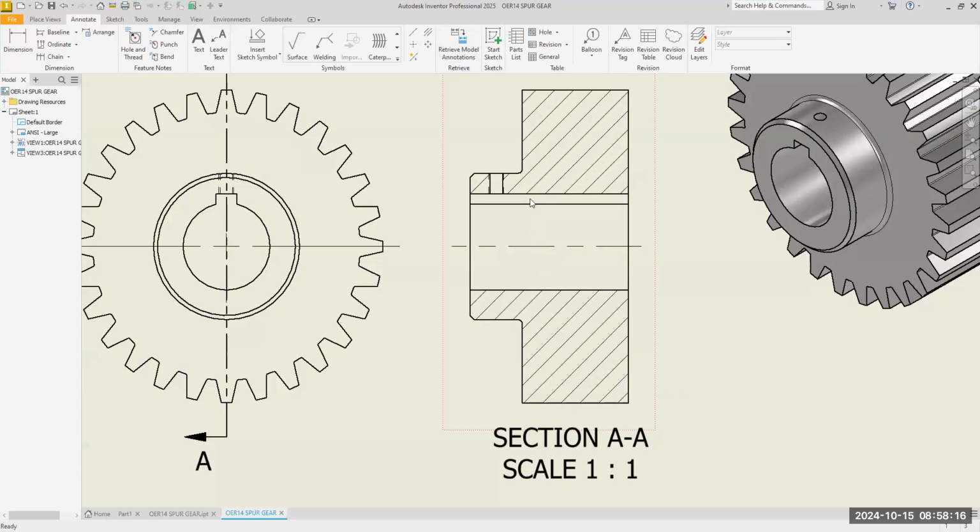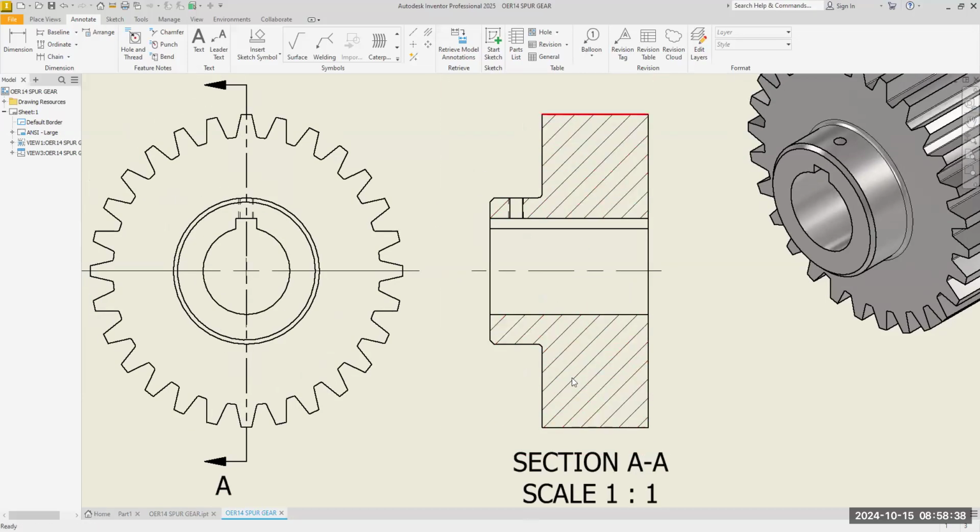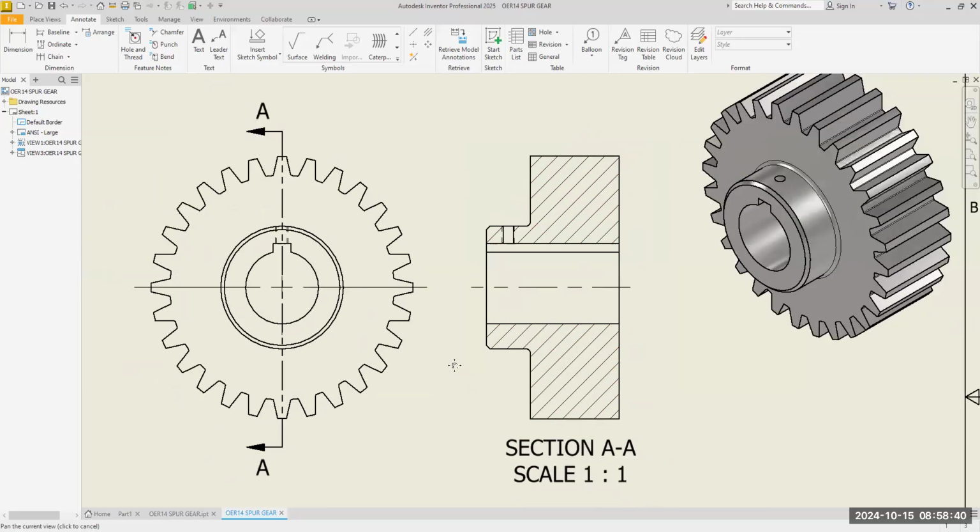The reason why I didn't pick these lines here is because I had to go back and find the 12 o'clock position for that circle, which is no longer there. We cut away the 12 o'clock. So if I pick that line and that line, that would not be in the center at all. But this is outer diameter, so that works.